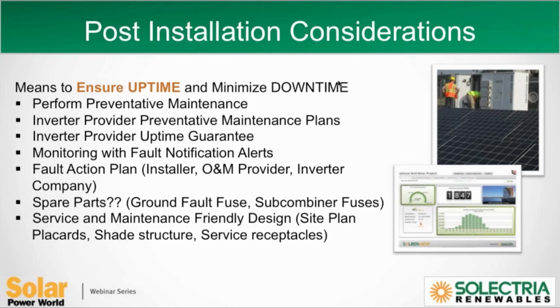I think there are several key service parts that every customer should have for their project to ensure uptime. Another opportunity is to have a fault response plan. Have your plan ready: your installer, the O&M provider, and your inverter company on hand to respond when you do have an issue. The inverter sometimes gets a bad rap because it's the only thing that really talks and provides feedback. Just because the inverter is down doesn't mean it's the inverter's problem. It could be a ground fault, or a DC voltage issue.